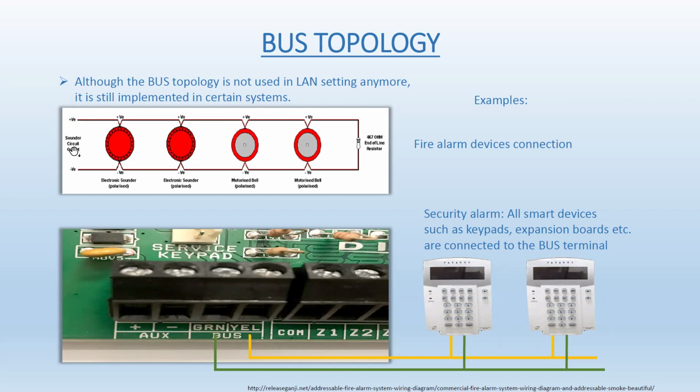So of course the people say, okay, fire alarm is beeping, are we in trouble? It says trouble. So they are going to call that phone number quite quickly, and the answer is, no, this is not a fire. It indicates trouble on the detecting lines. We're going to have to come and see what's going on. So don't worry, that's not a fire. Okay, so that's how that thing works. Now, if any of those devices trigger, you're going to see a dead short between here and here.